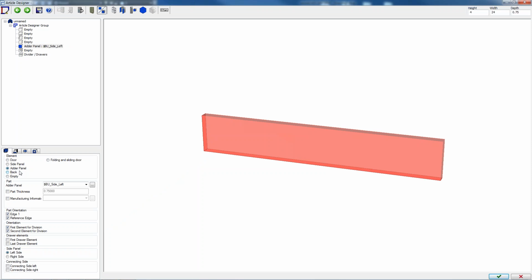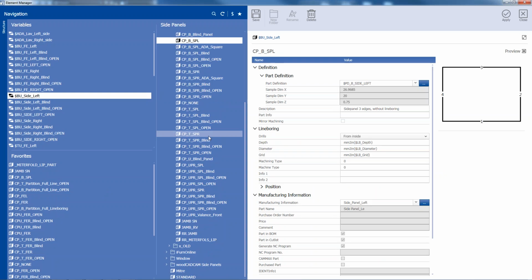All right, so we need a construction principle and a part definition, right? Do I have to have an underscore in the name? You do not. Only place you have to have an underscore is the order name or a variable name. Other than that, you can use spaces. Okay. What about special signs like slash? It's not going to let you use a plus, a dash, a slash, or an asterisk because those are actually mathematical operators. Okay. You can use some special characters, but not those 4.